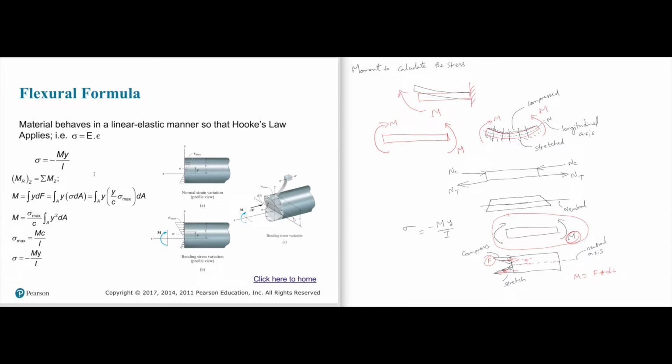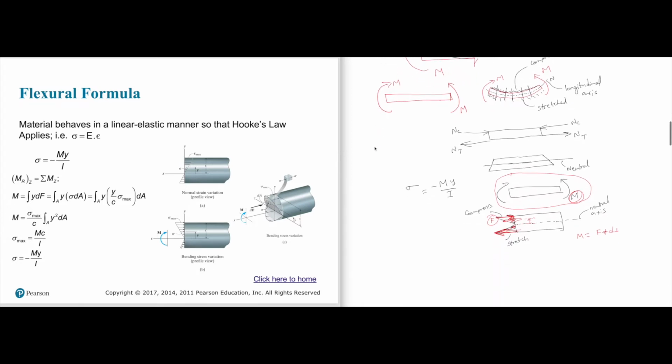And because this force is not constant at all locations, near the neutral axis the force is smaller, but at the edge the force is larger. Because of this, we say moment is some y times dF.